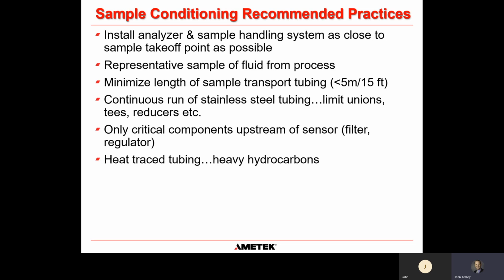The other thing is with the sample tap itself into the process, you generally want to go about 1/3 into the sample pipe itself, or the process pipe itself, to get a representative sample out of the process. You want to stay away from the wall and the wall effects that happen, and you want to be in a good, laminar flow area and away from the issues that happen along the pipe walls themselves.